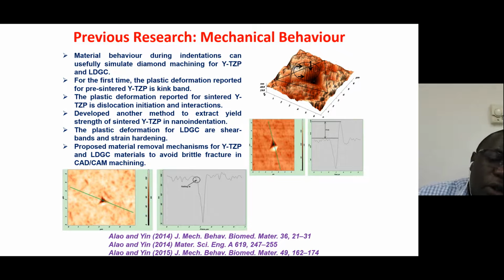So from there, you are going to generate the engineering stress strain curve. The first part here, beyond the elastic limit, is characterized by the yield strength. So this is the conventional way of generating it at microscale.